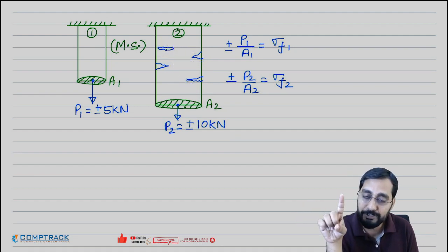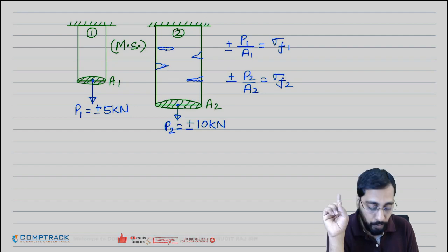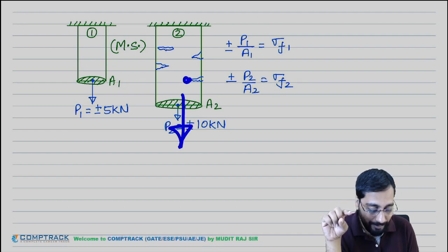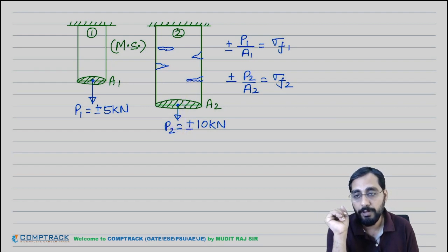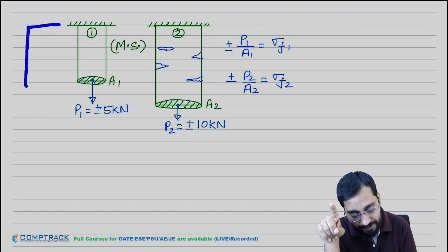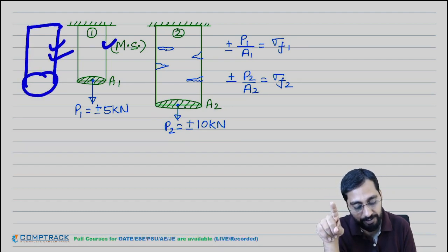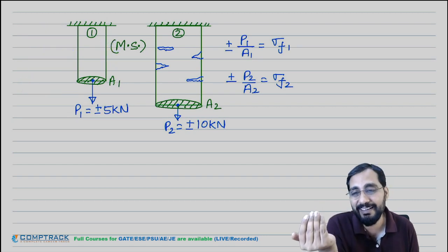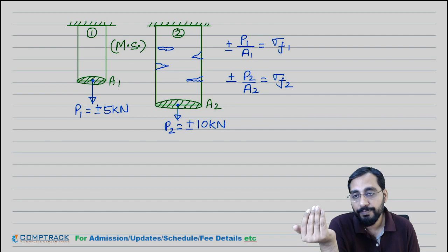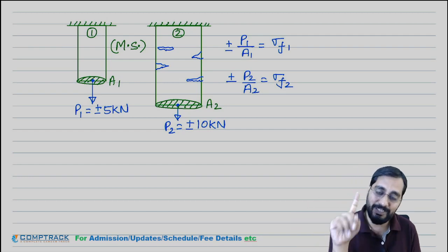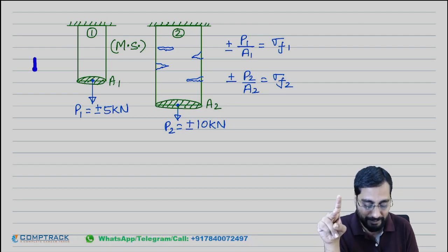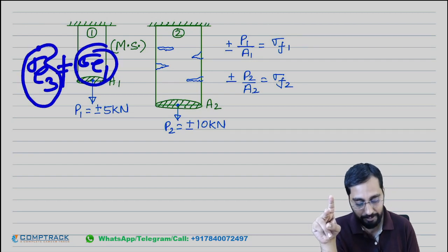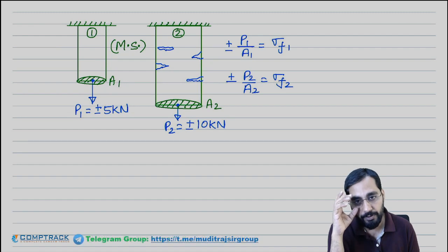And stress concentration due to fluctuating loading will make them more prone to failure. So even if both are of the same size, if surface finish is not the same, which cannot be identical, yes or no? So for the same material, same size, if surface finish is not equal, even then sigma E3 and sigma E2 will not, E1 will not be equal. Got the point or not?